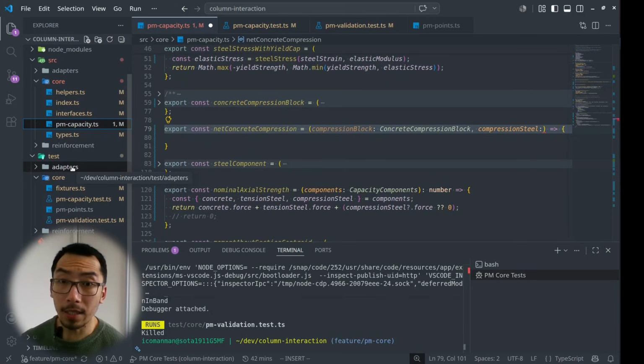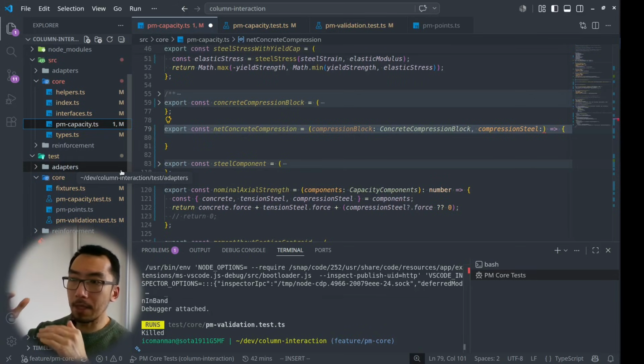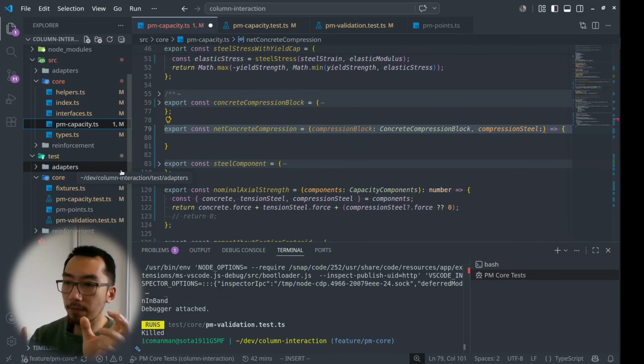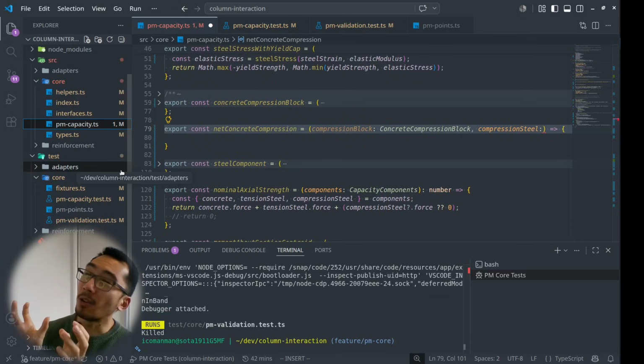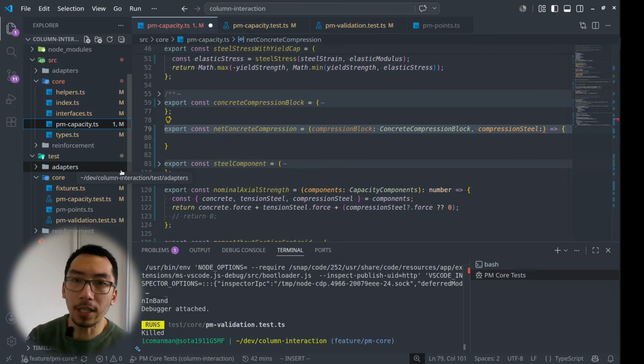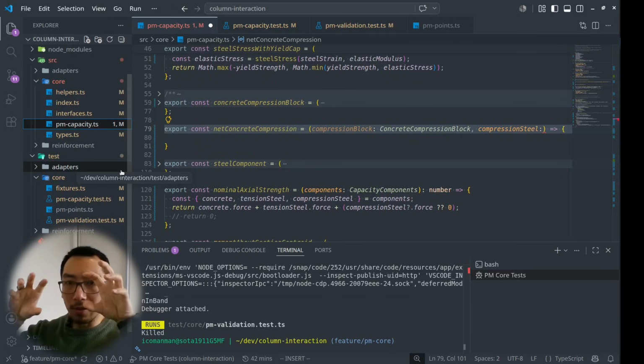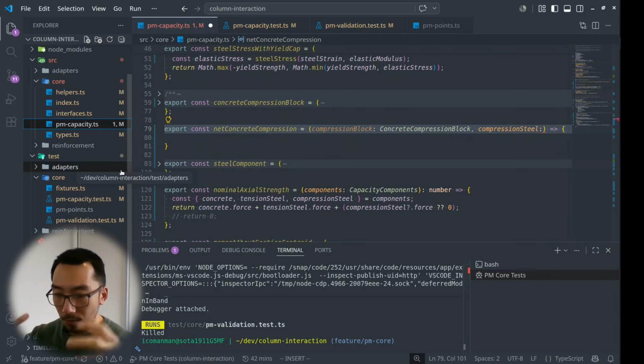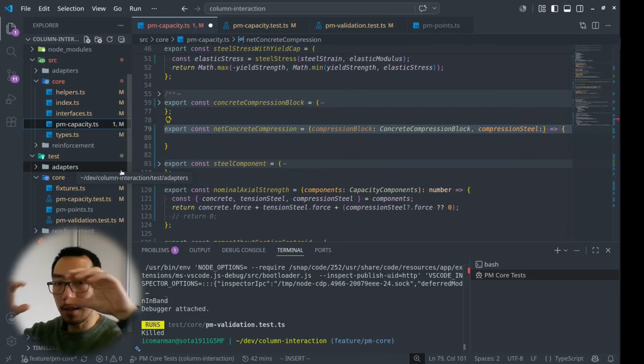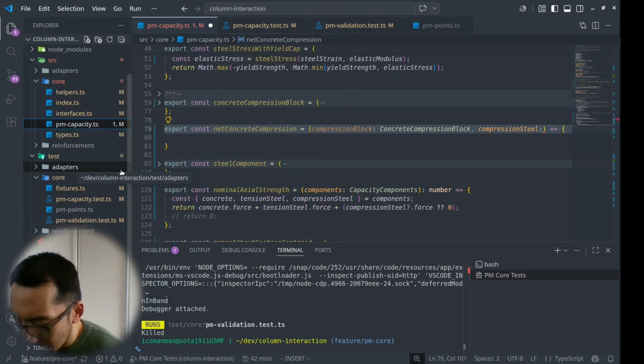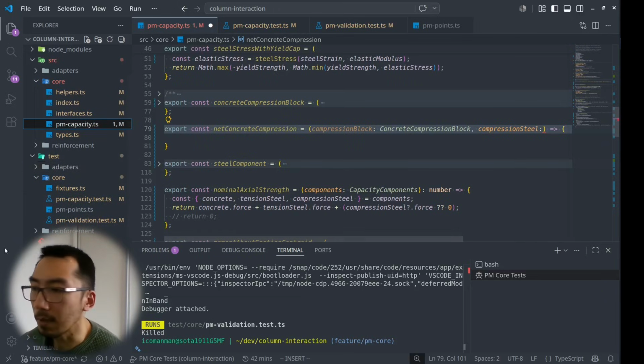But before I proceed, I just want to clarify that we're close. You saw the number earlier. It's 1965 versus 1991, so it's off by less than 30 kilonewtons. So I reckon that's the additional compression we took from the whole compression block without subtracting that tiny bit of steel reinforcement right there.